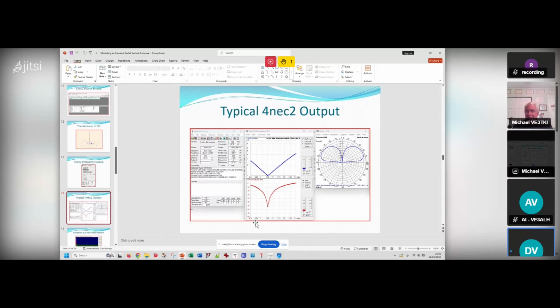One of the fellows down here was playing around with an end-fed half-wave, and someone commented to him. I don't know how this all transpired, but anyways, he ended up making a loop on the business end of the 49-to-1 Balun transformer. And he put about a 33-foot counterpoise on it, and it is absolutely performing tremendously on 20 meters.